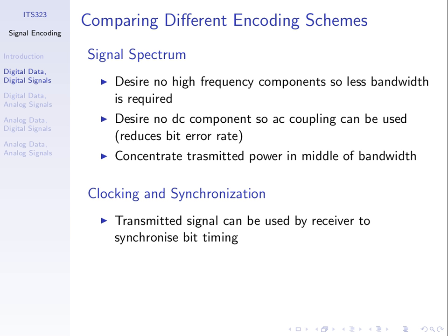This signal is low if we measure here, therefore it's bit 1 received. It measures in the middle of the next interval at time 1.2. The signal is high, bit 0.